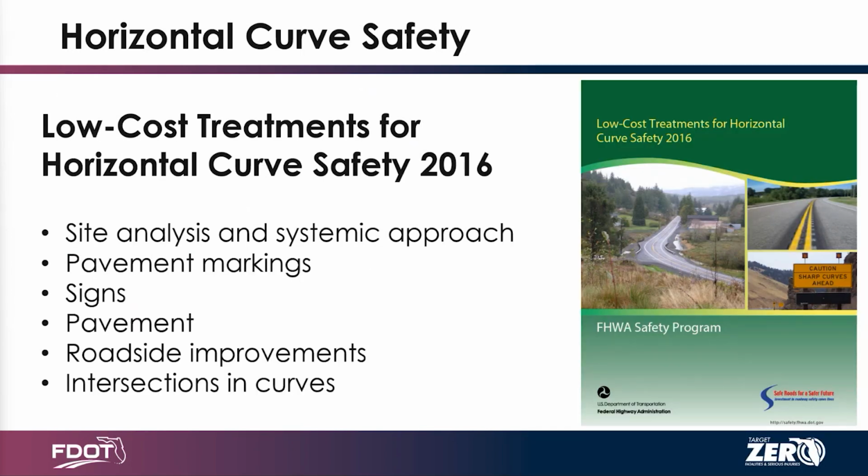There is a low-cost treatment for horizontal curve safety guidance that was released in 2016. They provide some guidance on site analysis and a systemic approach to horizontal curve safety. Some of the things they mention in there are pavement marking, signs, how to improve safety with the pavement, different roadside improvements, and what to think about when you have intersections in curves.